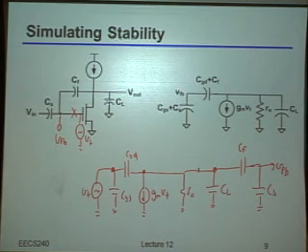But notice this circuit here is most definitely not the same as this, right? Or this feedback transfer function, most definitely not the same, right? In particular, CGS just got completely knocked out, right? Because we drove it with a voltage source. And as Rachel was saying earlier, even that CGD is not really being properly handled, right? So again, the real key point here is that if I want to do this in SPICE, I now have a problem, okay? Because I can't just break the connection there. I've actually messed up the loading, okay?